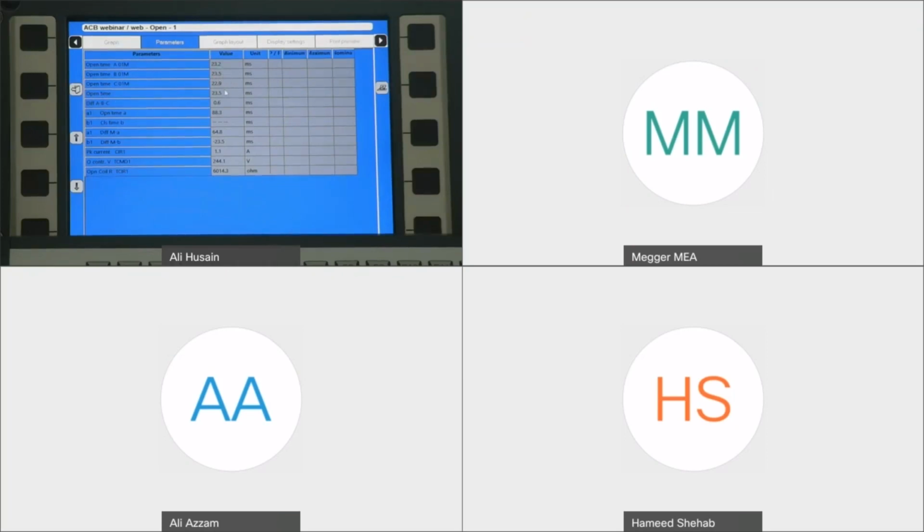And then we have some difference between the phases. It's showing here 0.6, it's calculated automatically for you. Also showing you the time for auxiliary contacts when they close and open. For this open operation, we are only checking the A contact. It's opening at 88 millisecond.